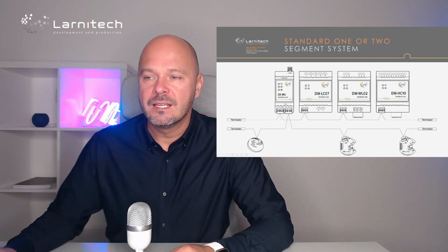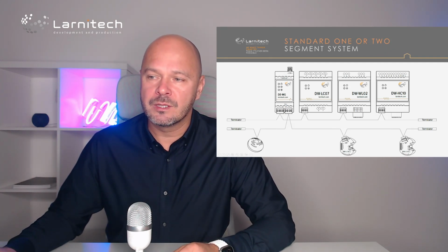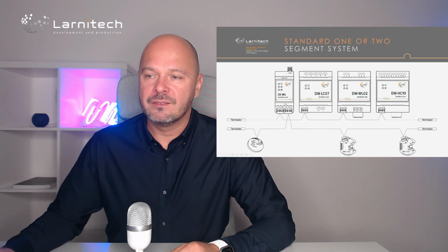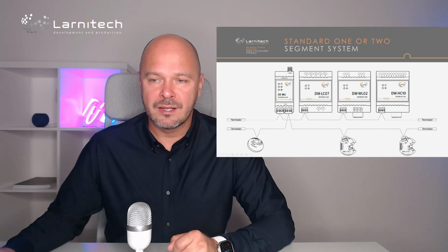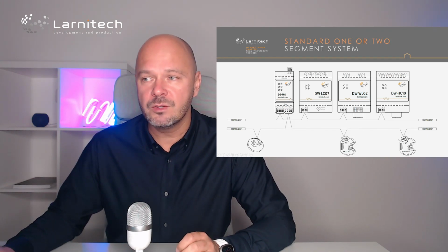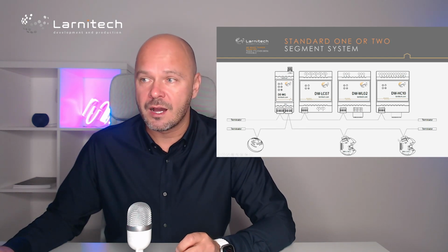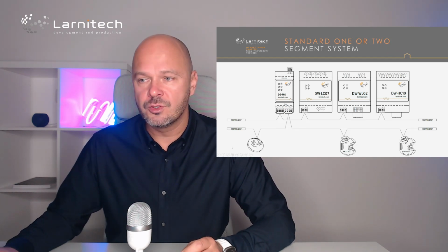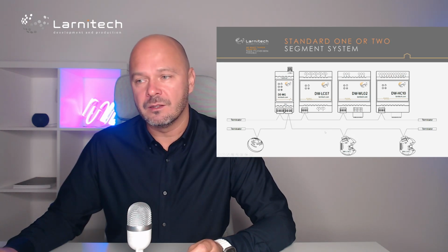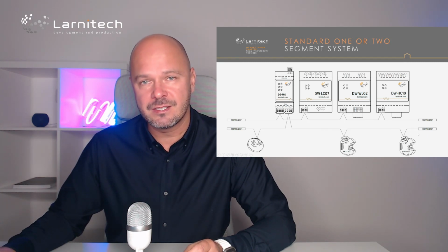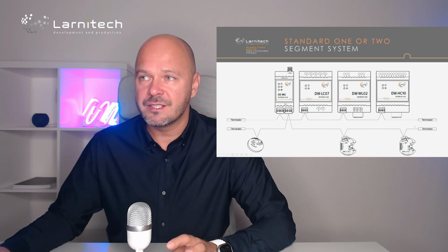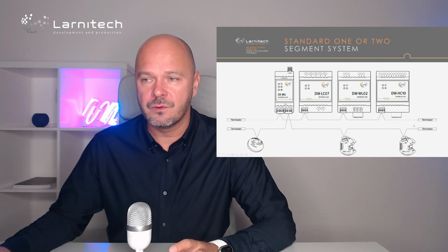So the first bus you connect by daisy chain some devices, and then the second bus you connect by daisy chain some other devices. Can we use star topology for our bus? No, you should use just this type of daisy chain, when one device and then another device, and so on. So at the moment, this is the standard connection for our system.